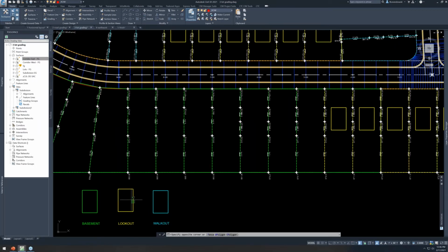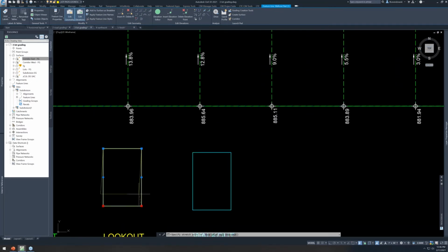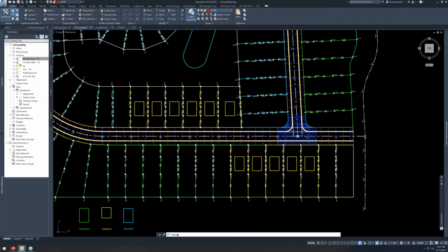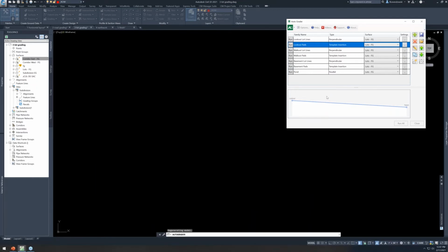Now, if the pad design were to change, okay, everything is based on this right here. So simply running that family again, lookout pads, you'll see an update to all these pads to match that new family. Okay, any parameters in the family, if I change those, right, once I get to my earthwork stage and I'm trying to balance my earthwork, I may want to make changes, not necessarily the pad size, but maybe the height of the pad and the lot in the first place.